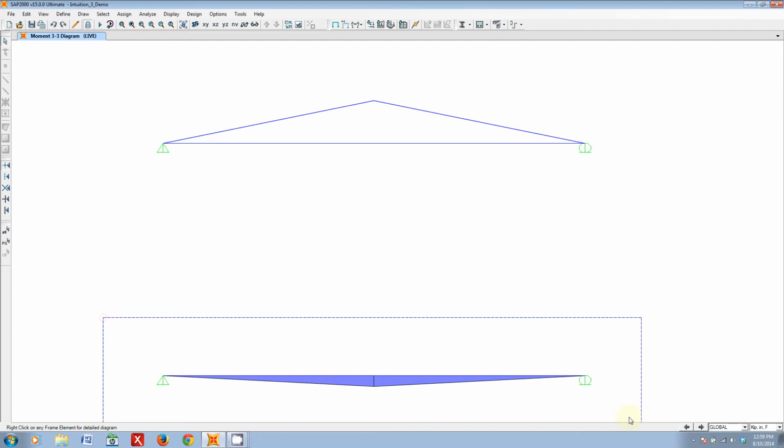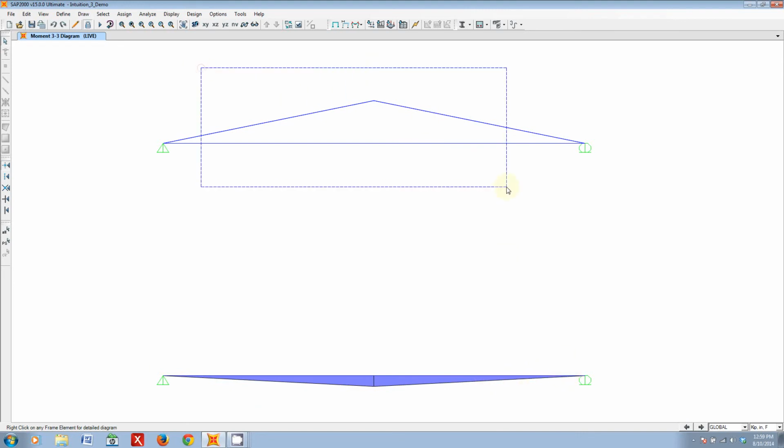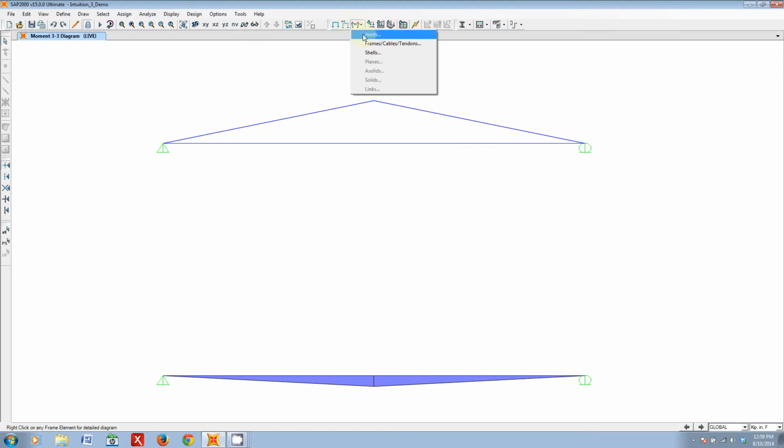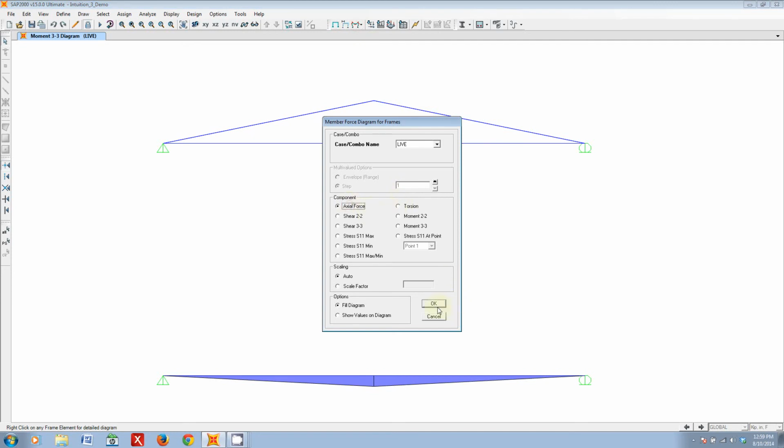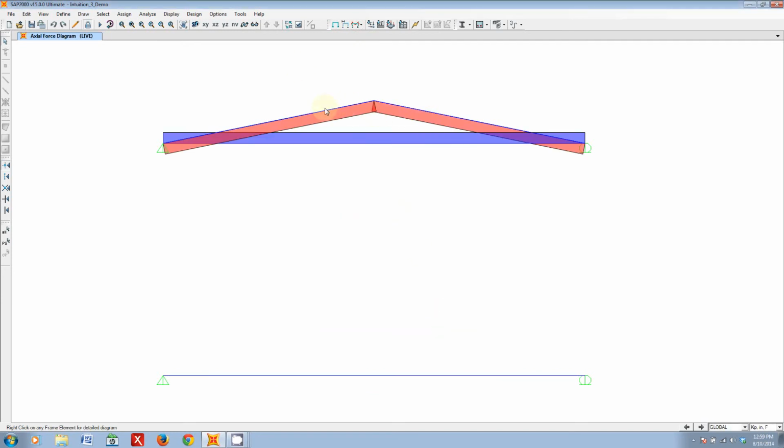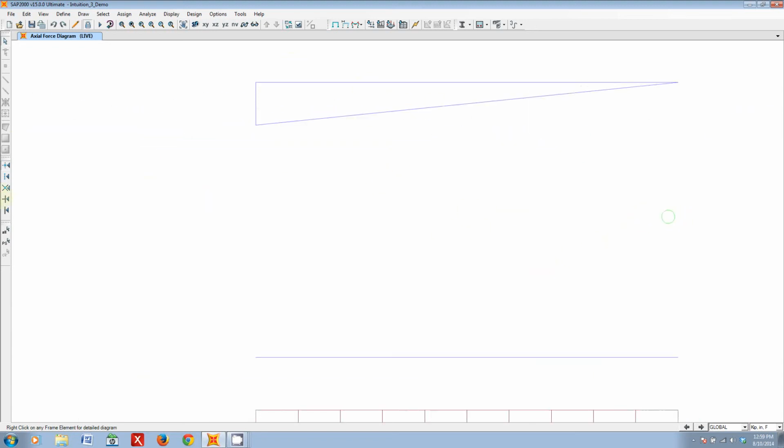But no, seriously though, you can draw a truss that follows the moment diagram of a beam. Check it out. And it actually gives reasonably good results. Check out the axial forces, and they're almost pretty much comparable between the top and bottom chords. You're getting a lot of efficiency out of using this kind of method because you're only making your truss as deep as it needs to be in the locations where there's the most moment. So, on to the next example.